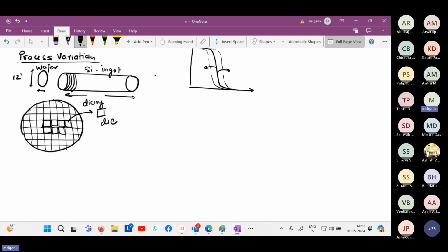For a PMOS transistor, what kind of substrate do we need? What kind of doping do we need in the substrate? So we need elements which have fewer valence electrons than 4, that is, which can produce holes, like magnesium, boron, aluminum. I said for P-type. For NMOS, what kind of substrate do you need? N-type doped or P-type doped? For NMOS, we need a P-type substrate.